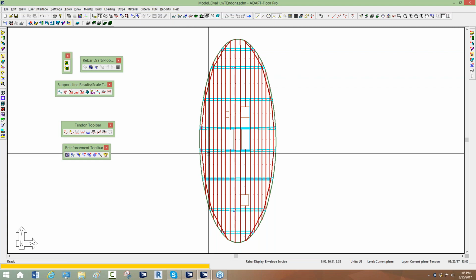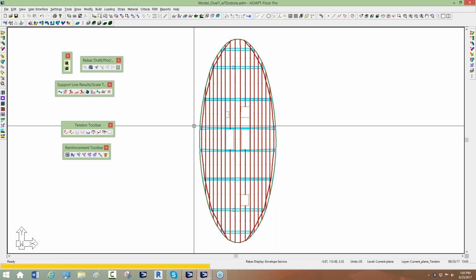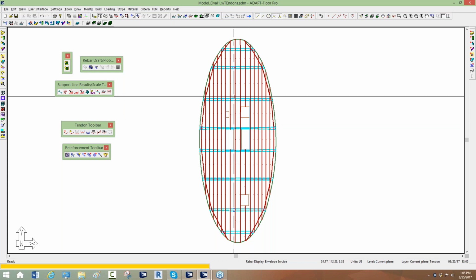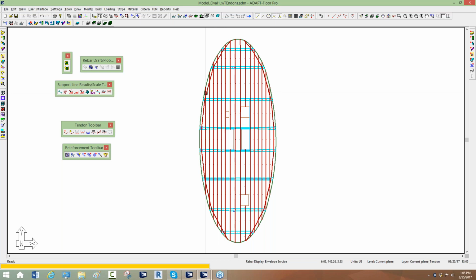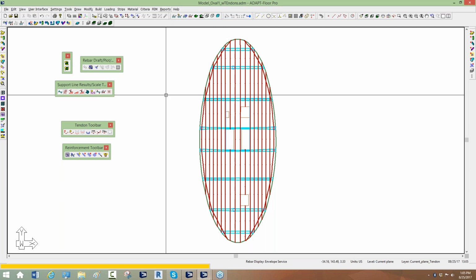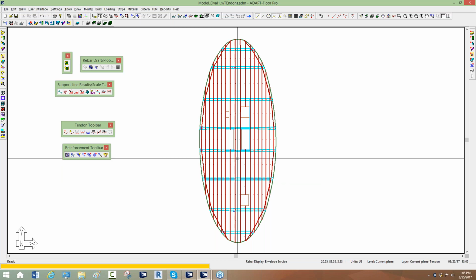The uniform cables in this model are a little bit different than how we're going to model uniform. In this case, we space them every 4 or 5 feet. We keep the spacing consistent within certain zones of the slab, and then we just adjust the number of strands. So we can scale that up to 2, 3, 4, 2.5. You can scale it up or down using decimal input also. We'll talk about that as we get to this point.